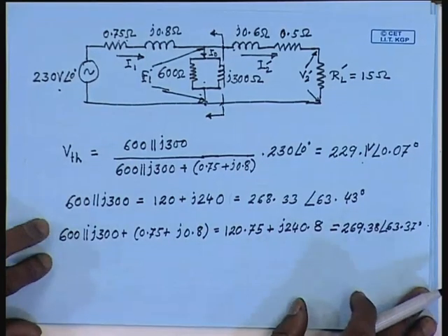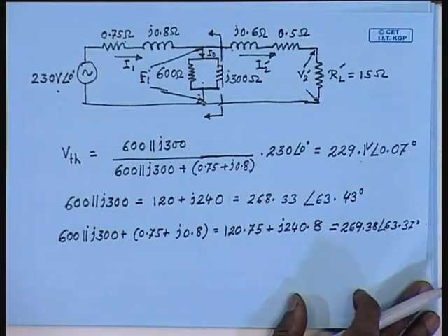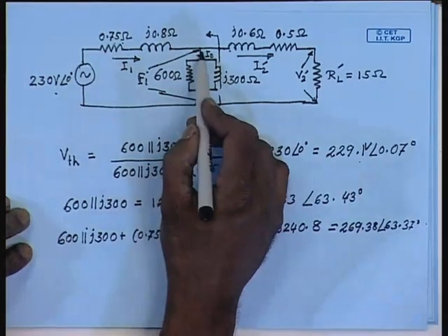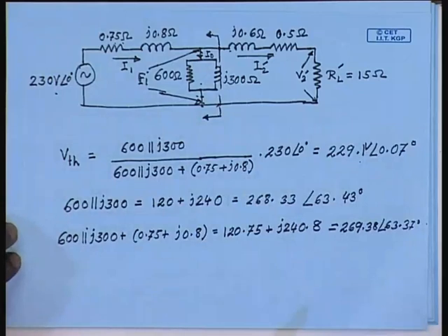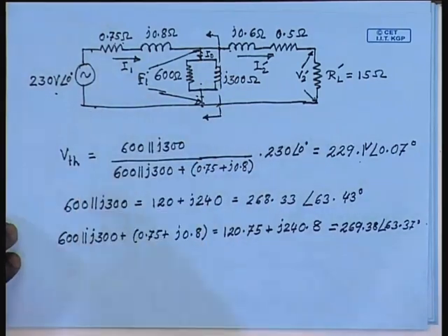Therefore, it possibly makes sense, in order to reduce the computational complexity, to obtain this Thevenin equivalent circuit by simply omitting this part and connecting this right across the supply voltage. In fact, that is what is done in most practical cases, since the results that are obtained by that approximation are not very different from this exact equivalent circuit. We will shortly see that.